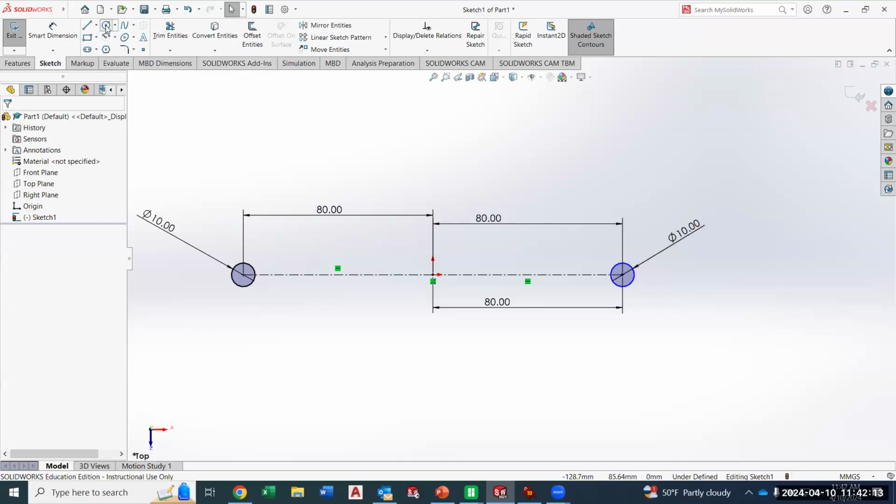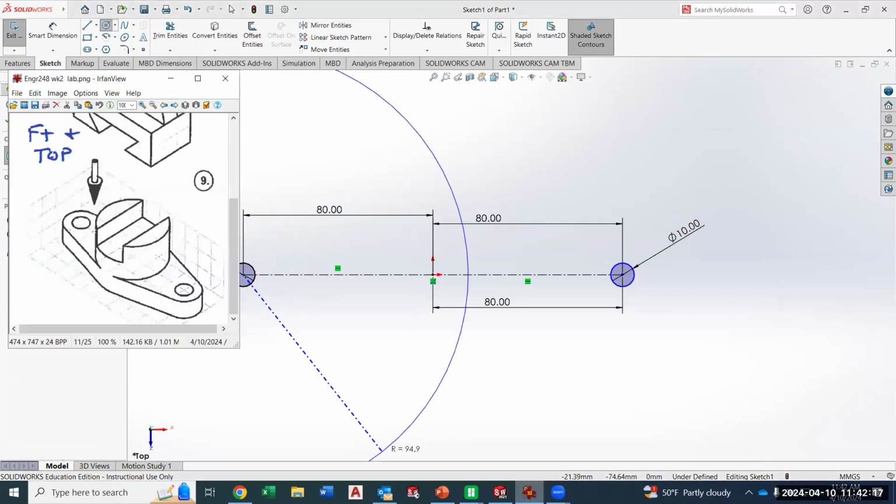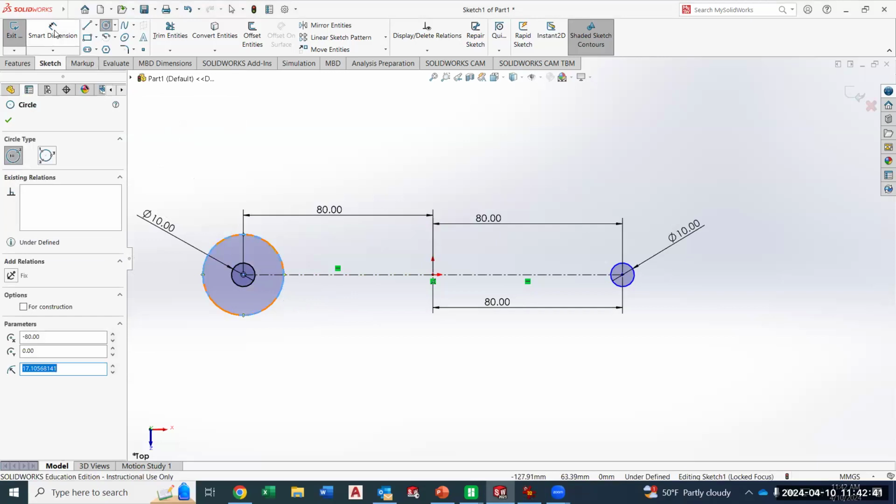All right, so now I'm going to put these outer arcs on. And they look to be half a grid more, right? So that's 5 millimeters more. So if this was a 5 millimeter radius, or a 10 diameter, now this is a 10 radius or a 20 diameter. So that's the way I'm going to put it. A 20 diameter.